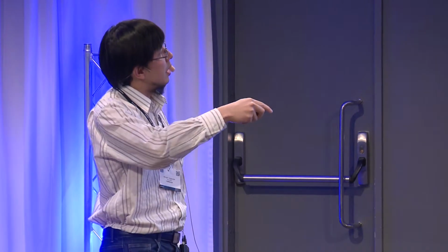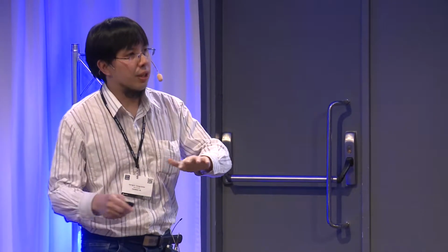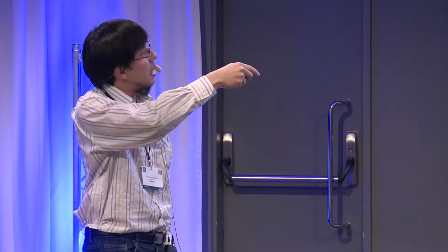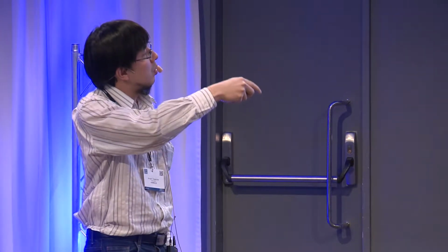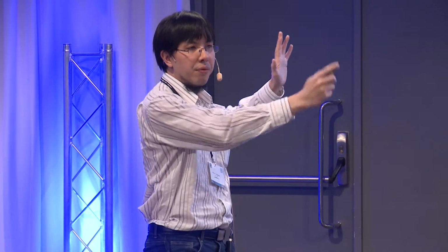Then this is when you have one single sample, it looks like this. But in order to extract the feature to build a model, one way to extract the feature is you take the peak-to-peak signal. So this way you could quantify or summarize this waveform into a single number.